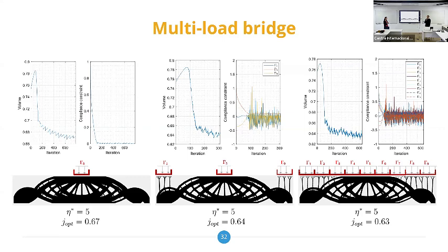If you keep refining the mesh, and generally if you don't have control of the scale, you are obtaining thinner and thinner bars, that's correct. And that's one big topic in topology optimization, which is the existence of solutions. But this problem is already solved, okay? Maybe I didn't mention it here, but when we implement compliance constraints, we solve the elastic problem for this problem.